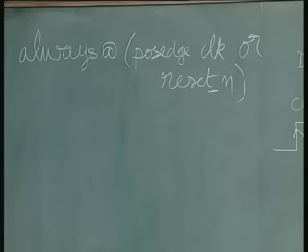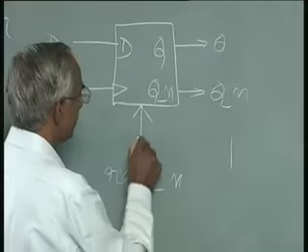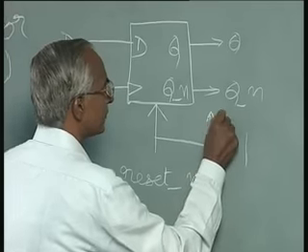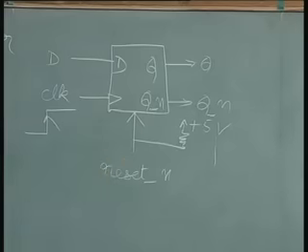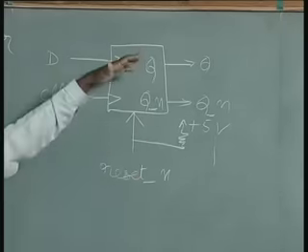Suppose the cable snaps, it should return to a safe value. So what we do in the circuit is, where the reset push button ends in this PCB, we just put a pull up resistor. If it is +5 volt operation, this is the thing. So when a cable snaps, it takes it to a safe value as such.